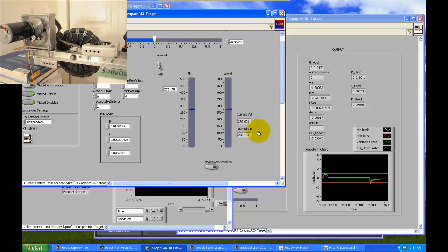You'll see here we're about 2 inches off. So play around with this, and if it is 0, and the reason why I always stress there should be some acceptable error. If it is 0, what that tells the controller to do is make sure the current value matches the desired value. So what's going to happen is the PID controller, any PID controller, is going to constantly iterate and try and make these values 0. And that's going to mean oscillations around your set point depending on how well your gains have been tuned.